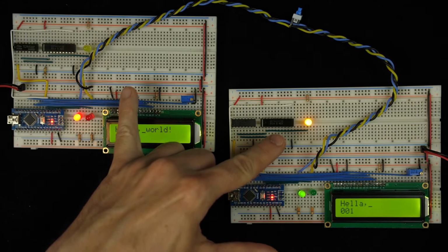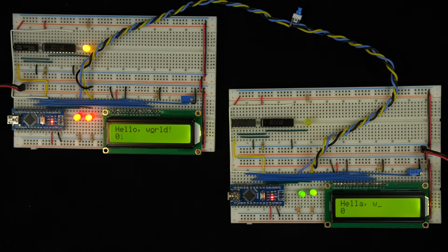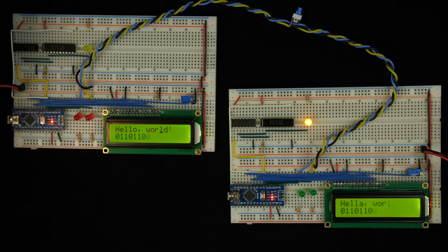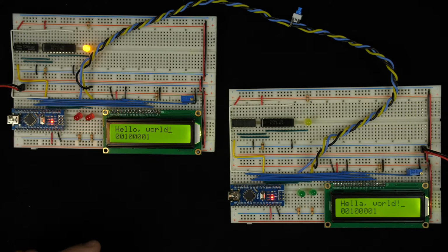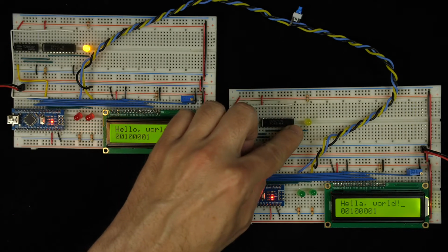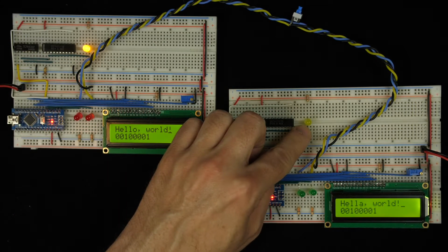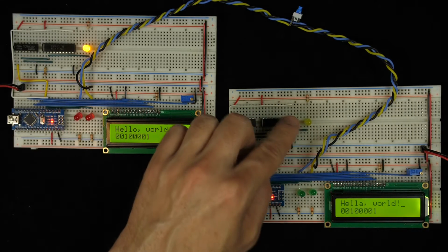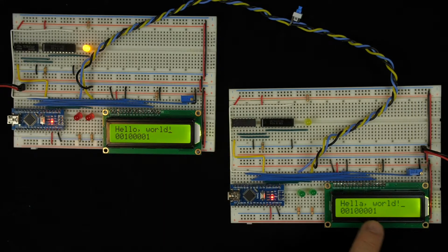And already you can see the parity bit is out of sync. If we just speed this up so it finishes up, now at the end of the message, we can see the transmitter thinks it sent an odd number of 1s because the parity bit is on, but the receiver thinks it received an even number of 1s because the parity bit is off. So that means there was definitely an error, and this message here, hello world, is apparently not what we sent.